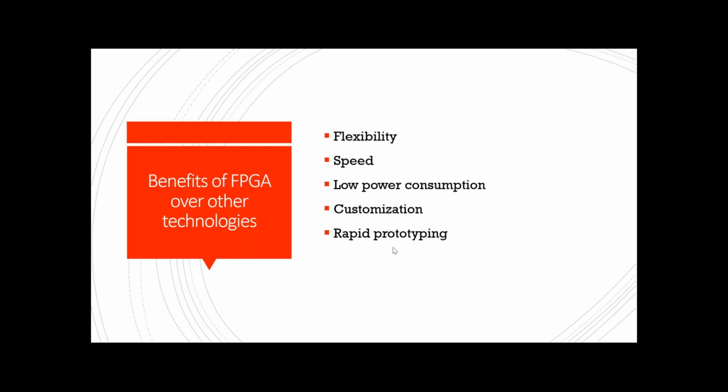Low power consumption: compared to general purpose ICs, GPU or CPU, FPGA can be made a low power consumption device. But compared to ASIC, ASIC consumes lower power because it has limited hardware, right? So again, it's all trade-off. You have to understand which one to use. Customization is highly customizable. I kept on telling this repeatedly: you can modify it the way you want, right? It's not something like one-time programmable.